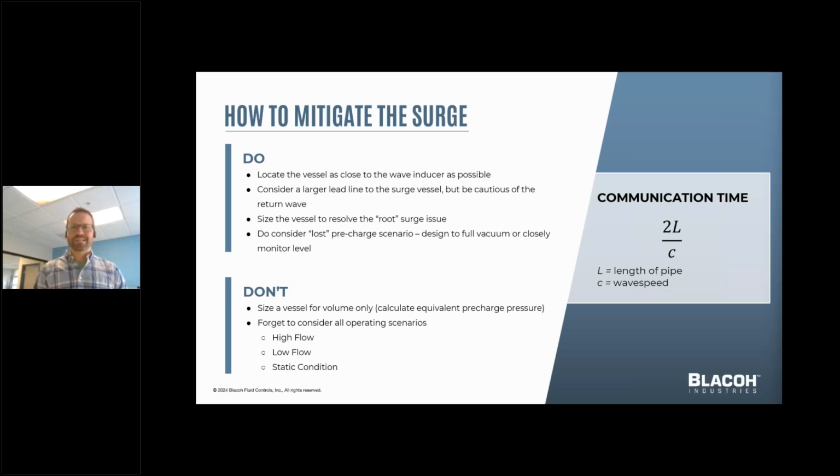There's some other things there about sizing the vessel and thinking about the root surge issue. What's actually causing the problem? And will a surge vessel actually fix it? There's a lot of transient analysis that needs to be done to actually size these vessels correctly. And it can be a complicated process, but it's worth the time.